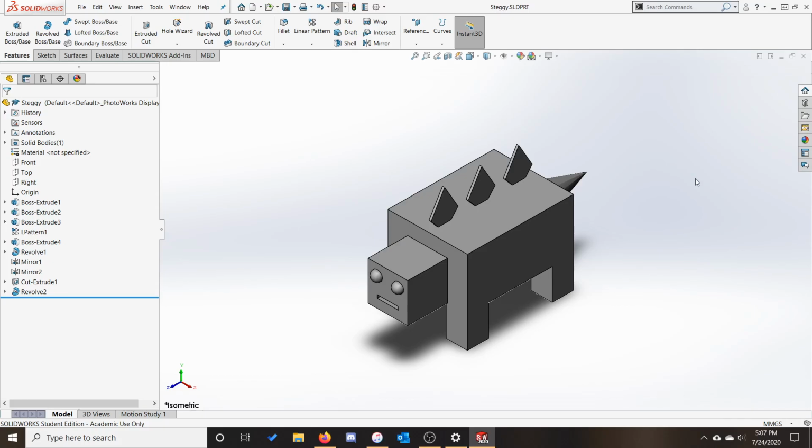You may want to ensure that a dimension remains equal across sketches and features, or you'd like to enforce a mathematical rule that states that one dimension is always twice another dimension. You may also have a collection of models that are all fairly similar but have different numerical values or feature suppression states. Equations, configurations, and global variables allow you to bake these rules into the model itself.